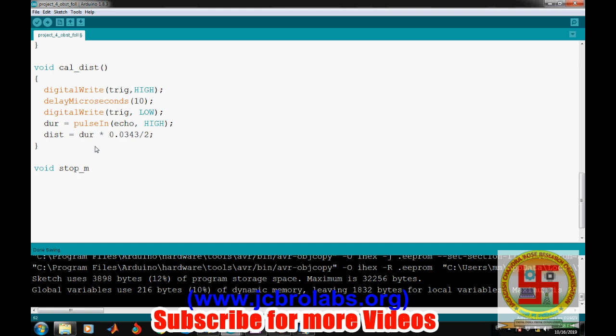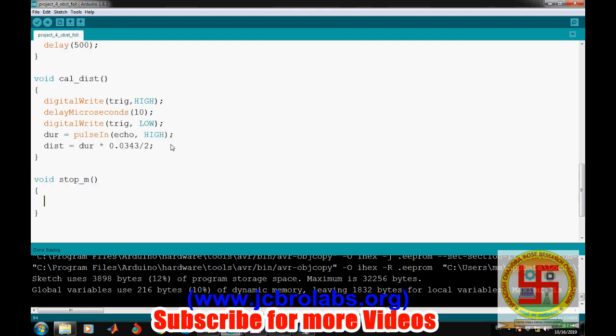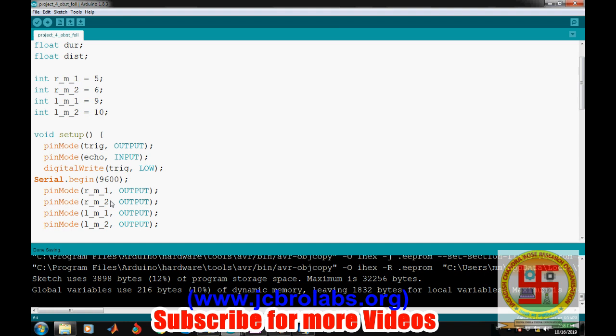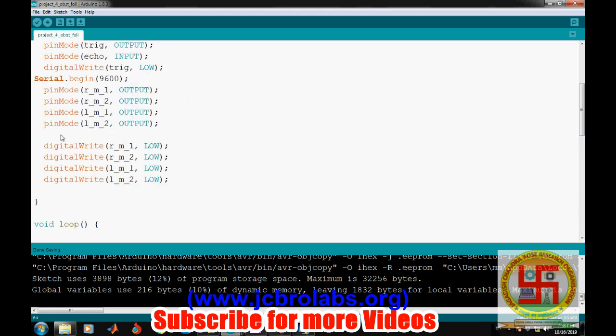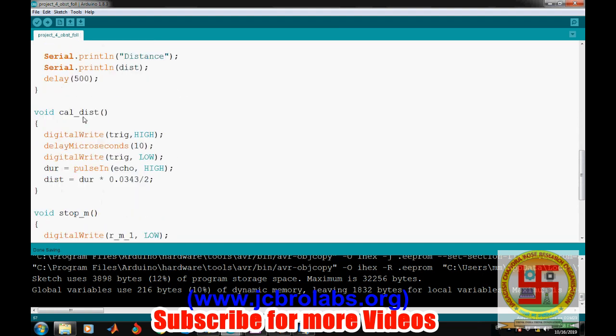We are intentionally using this function to make you familiar with how to use functions in an Arduino program. We don't need to pass any value there, because the pins of these motors have been initialized globally and the pin mode has been specified, so we can simply use those functions here. We use digital write on the left motor, because it is a stop, so it will remain stop. So stop underscore m.